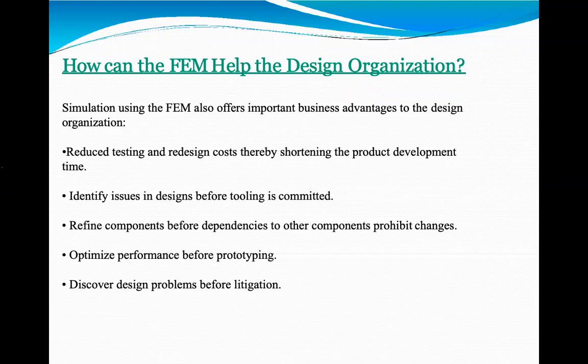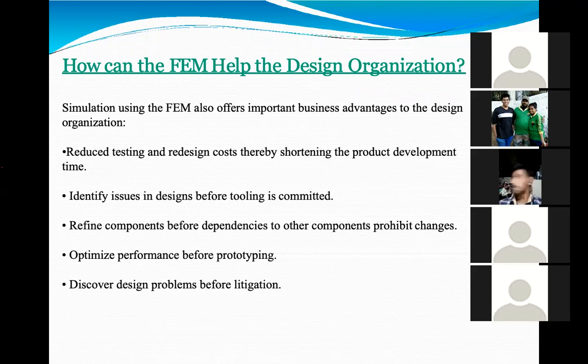You go back to your analysis report and check whether this was the critical area, or whether the stresses in this area were higher. We will check at which location the stresses were higher for the same product. If the location matches where it has failed, then we can say that our analysis results are matching, and we can modify our design at this location.